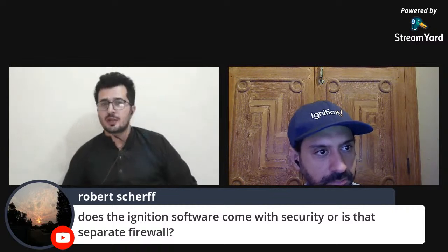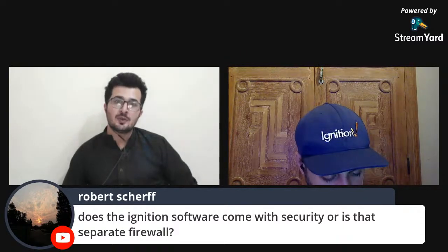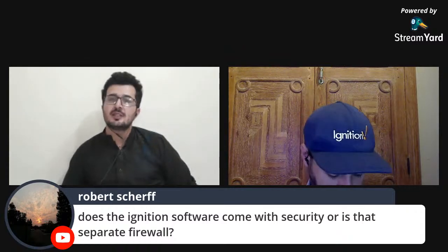Yeah, it depends. I want to add a little to that, Numan, because I'm currently working in OT cybersecurity. There is one system security where you are securing the software first, whatever the SCADA software is. If it's Ignition, or Siemens WinCC, whatever, you have to first apply the cybersecurity measures at the software level. Once that's done, then where it's installed, for example Windows, which should not be Windows 7, at least Windows 10, you have to harden that particular Windows. If it is installed on a Windows server, then you have to do system hardening for that.